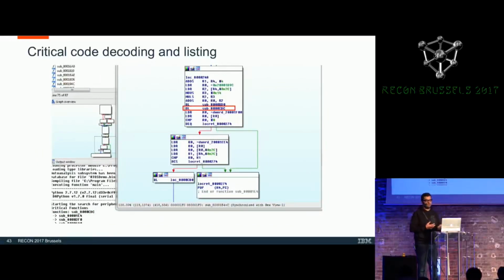Now, enabling and disabling the interrupts is not that linear, because each interrupt will have different priorities, and there are a couple of priorities that will actually make the kernel of the RTOS stop and execute the handler that handles that interrupt. So it really depends on the priority of your code. Again, there are registers that are used to define the priorities of each handler, and again, that's just a register inside the MCU. You just need to look at the documentation, and you'll have exactly what register we are talking about.